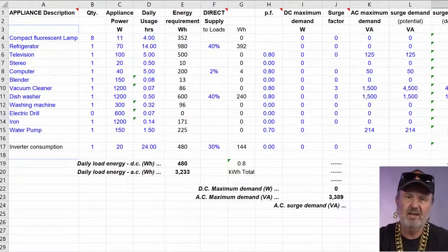So power factor, why does it matter? Because, as I said earlier, it's actually part of the demand that an inverter system in a standalone power system has to deliver. So why am I telling you all this? Well, let's go back to that load sheet where the customer had a bunch of loads. Now, you might be designing a system for a home with some loads that have a high power factor, such as motors, pumps and motors particularly, or fluorescent lighting has a negative power factor, which you might think helps, but probably doesn't.